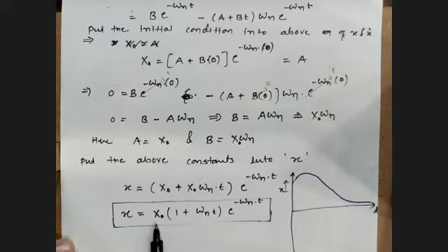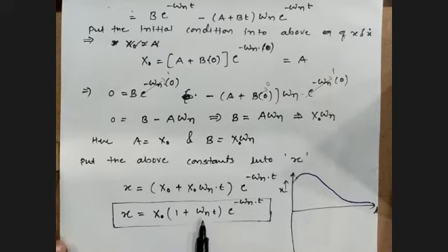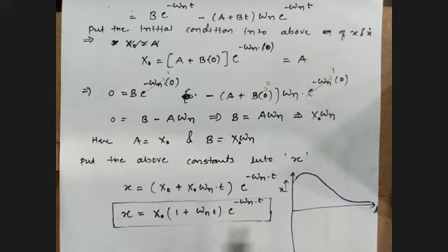So this is considered a constant value. Omega n, that is your natural frequency. You cannot change the natural frequency until you change the mass and stiffness, right? So that is also constant for a particular system. So the only dependency is on time. If you change the time, you will get another value of displacement, right? So at a particular time, you have this kind of response, right?